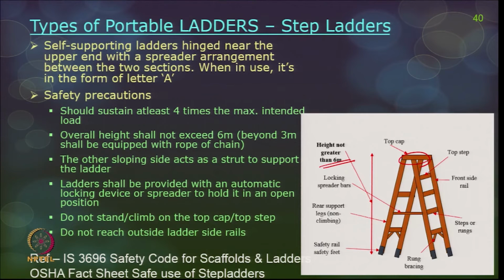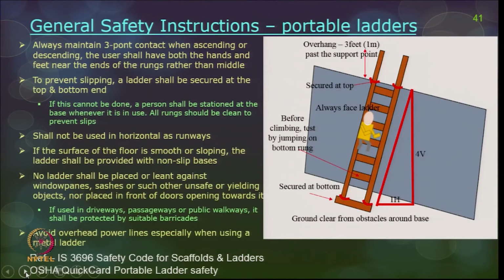Do not climb or stand or try to do anything on the top cap or the top step, and do not reach outside your ladder side rails. Again, it is primarily the awkward posture. Do not try to extend or go above the side rails to reach out for something. That is not advisable and you may have a fall hazard.